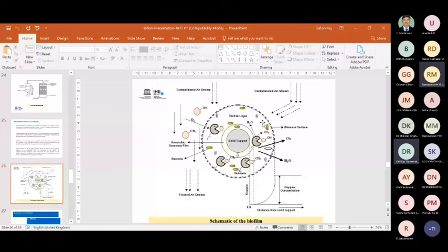And the fourth mechanism is adsorption. Adsorption can happen when you have a packing material that has large pore surface and a lot of functional groups, which will of course adsorb, like activated carbon. If you use activated carbon as a packing material and you have a biofilm that has grown, part of the removal can also be attributed to an adsorption-governed process rather than biodegradation. And of course, biodegradation will also be there, and both of them will be collectively contributing to the removal.